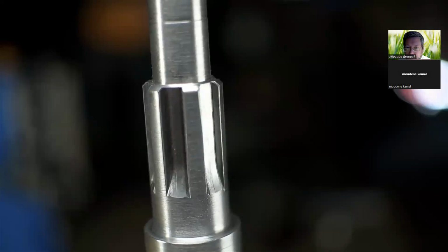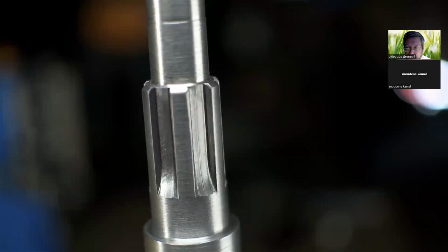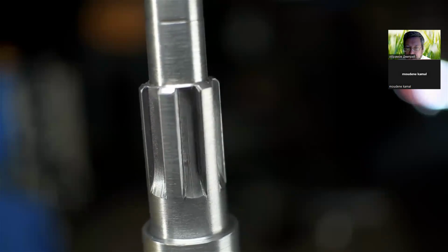And there it is. It's probably not going to end up on the cover of National Geographic, but according to the numbers, this thing should work. I did my best to get in there and deburr it with a couple of small files and a stone. I didn't do an exceptional job. You can see some scuff marks here and there. I'll probably hit this with a little bit of Scotch-Brite or a wire wheel or something just to make it look a little more uniform. But as is, there aren't any sharp corners, so no one should get their hands torn up on it.